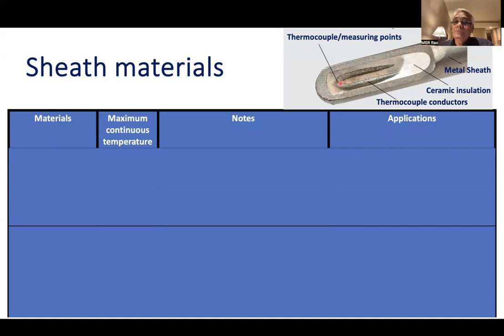Welding means you normally use another element. So we are not using a third element here. It is a combination of these two dissimilar metals, A and B. You heat them to very high temperatures, and you're forming a junction of the AB elements itself, without bringing in another element like lead or indium that is normally used in the process of soldering.